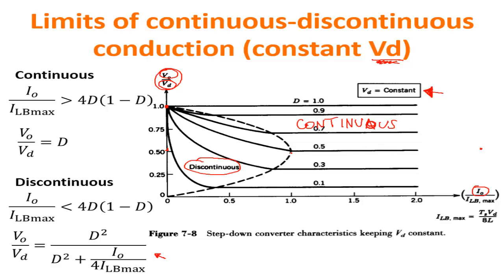If the current becomes lower than this value, then we need to progressively reduce the duty cycle in order to keep the voltage constant, because of course you cross these curves at constant duty cycle, going from 0.5 to lower and lower duty cycles. Of course, this type of behavior has to be taken into account by the logic circuit, which actually performs the regulation of the switch converter.